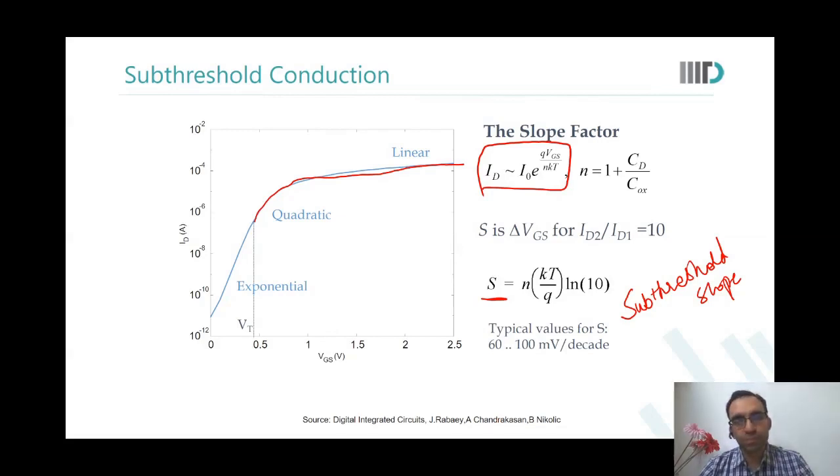I have a doubt from the previous slide on short channel. The current is decreased. Why is it decreasing? Current is charge flow per unit time. In short channel, the charge in the silicon will be the same, no? Yes, but its velocity has decreased. Velocity can no longer increase as much as you wanted, due to velocity saturation.